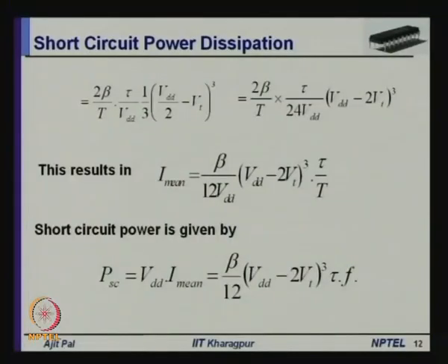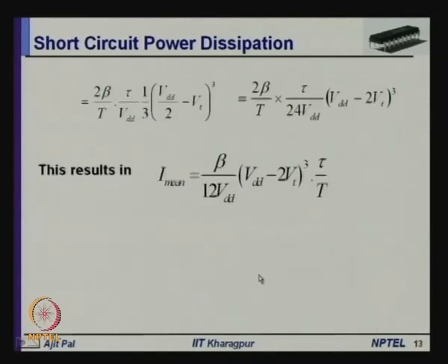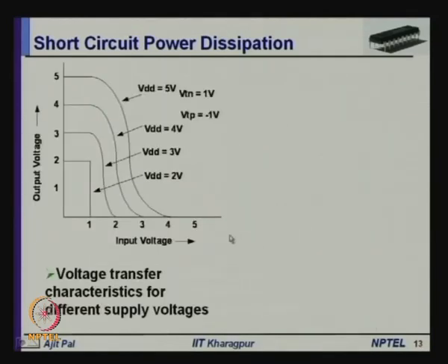So, this is the short circuit power dissipation expression, and obviously this particular current is significant in some circuits when the input is changing slowly.